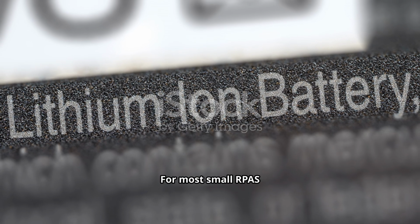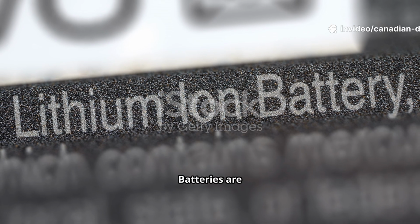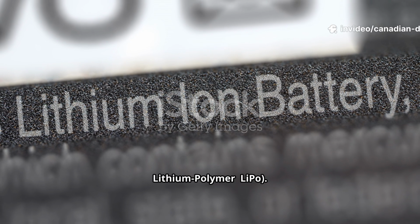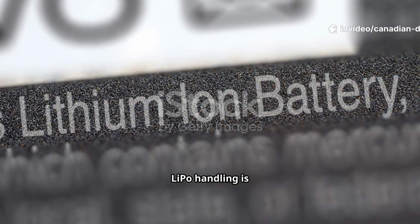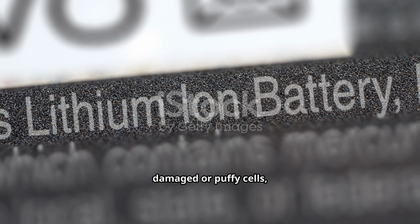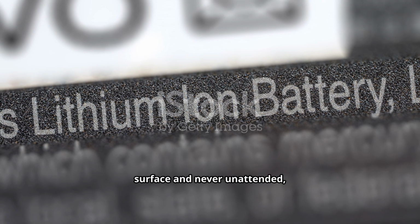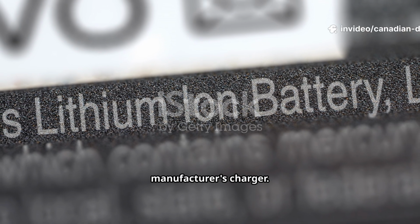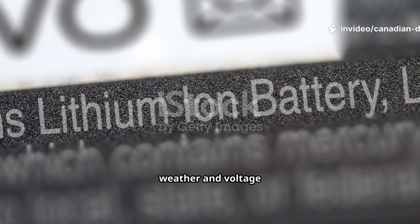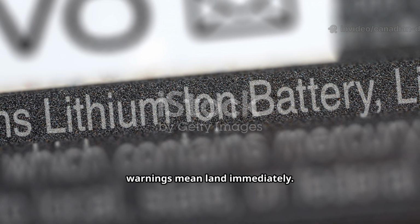For most small RPAS, this is electric: batteries, brushless motors, and ESCs. Batteries are almost exclusively lithium polymer, LiPo. LiPo handling is critical. Store and transport in a fireproof bag, never charge damaged or puffy cells, charge on a non-flammable surface and never unattended, use the manufacturer's charger. LiPo performance falls in cold weather and voltage drops during flight. Low battery warnings mean land immediately.